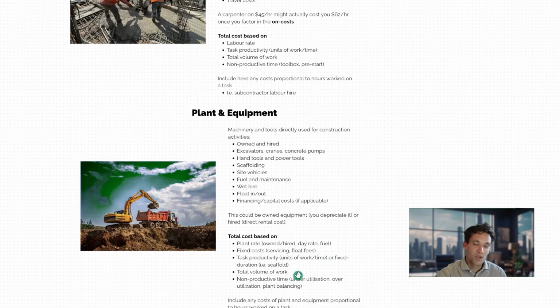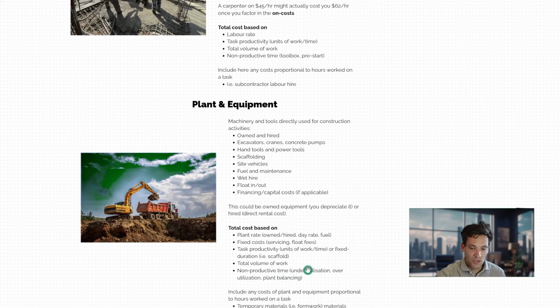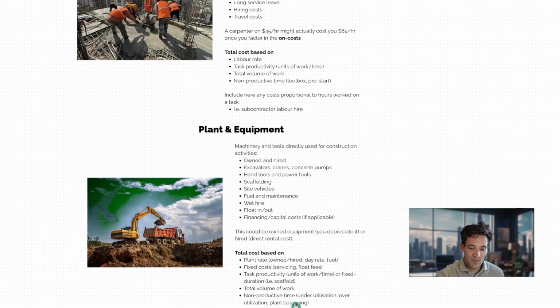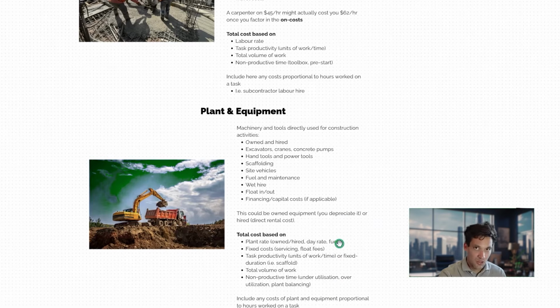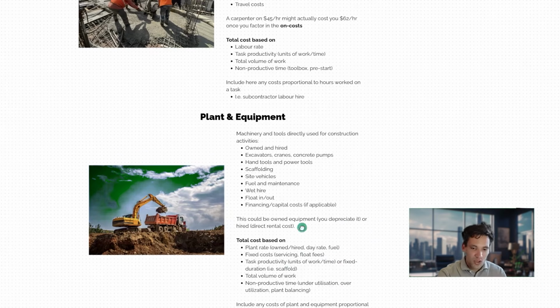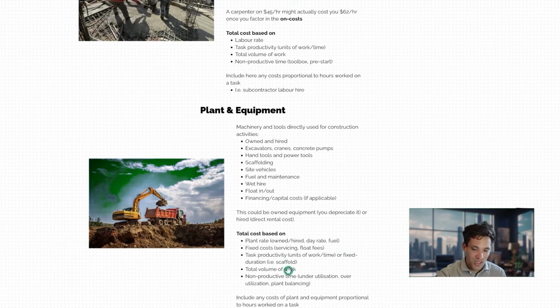And then as well, if we are talking about production rates, it is going to be a function of the total volume of work. Same with labor, we're going to have this non-productive time factor depending on how much the plant's actually used. You can also have overutilization of plant where, for example, you're paying a daily rate for an excavator, but if you're also doing a day shift and a night shift, you're not getting charged anything extra for the hire during the night shift, which would reduce the plant rate. So plant, more so than labor, you have to understand the utilization of the plant to price the works properly.